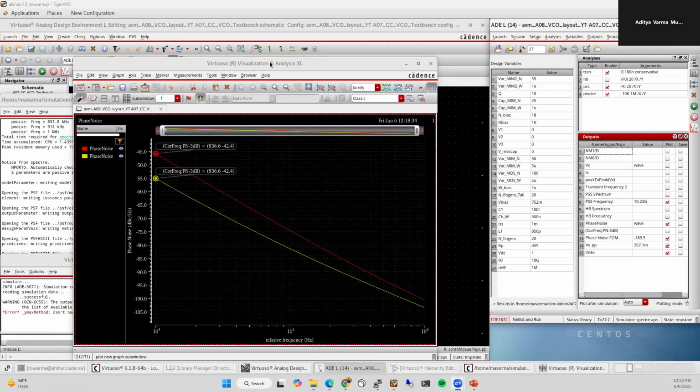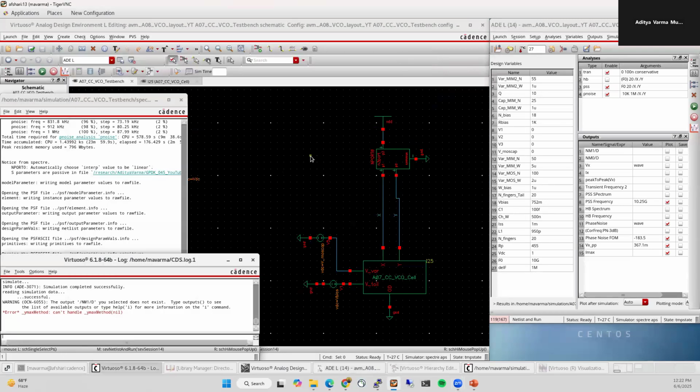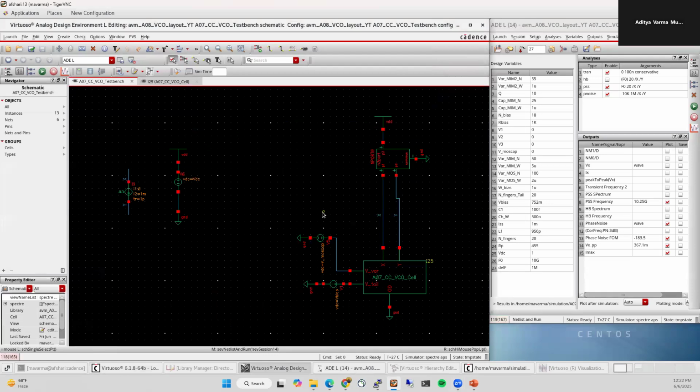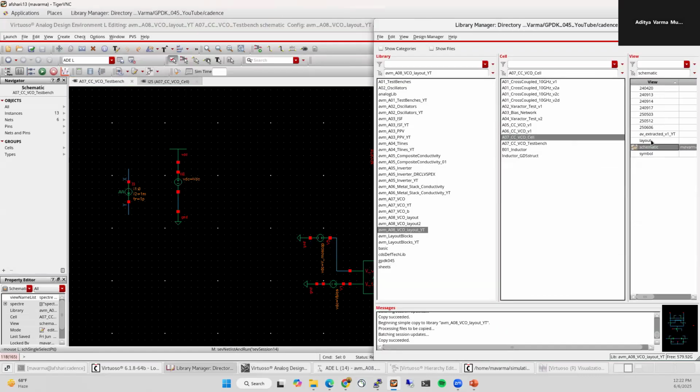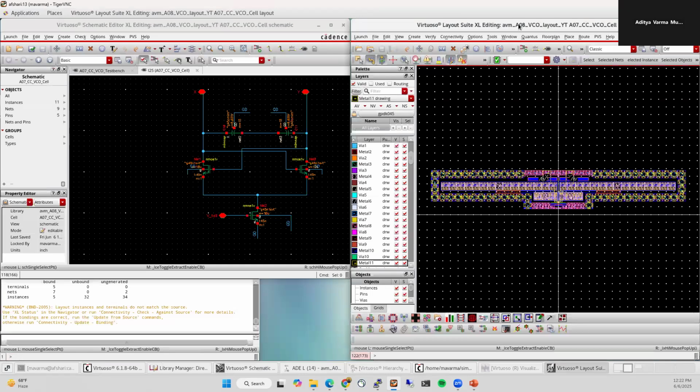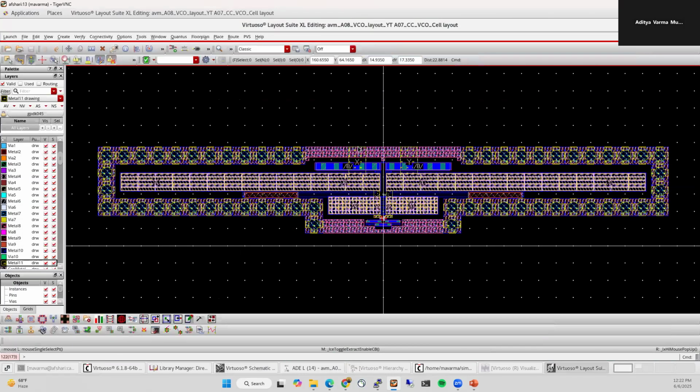Okay, so we have a nice layout now. We've done parasitic extraction, we've simulated the inductor separately, and we've added that to the simulation using this file. So what is really left, right? There are two things that we still need to look at. What are those things? In the layout here, we have connected the inductor out here. But in HFSS, if you remember, we placed a port on that inductor, right?